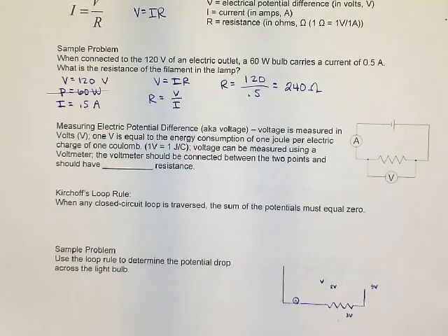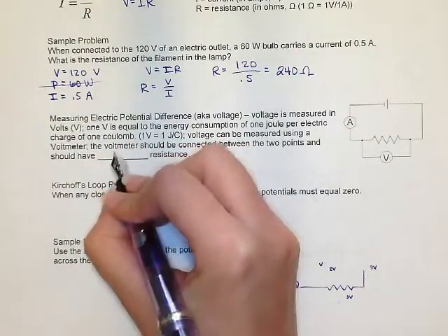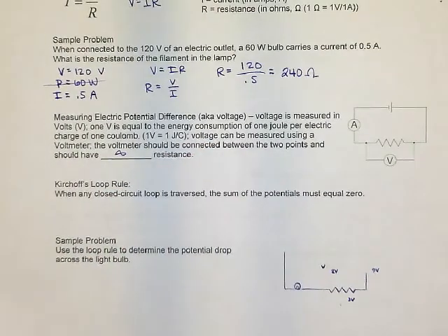Okay, there's some grammar there. We always say the current flowing through the resistor. We always say the voltage across the resistor. Like with the ammeter, our voltmeter shouldn't mess with the circuit itself. So we don't want any current to flow through the voltmeter, because that's going to mess up how much flows through this resistor. So your voltmeter should have essentially infinite resistance, or a really, really big resistance, to prevent charges from skipping through the multimeter instead of going through the resistor.